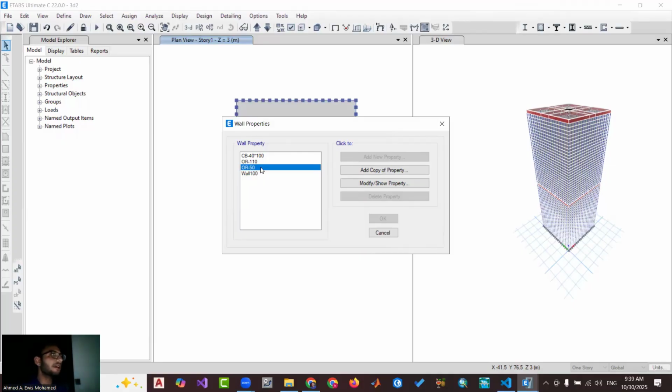Do you know the outrigger? Yeah. So the outrigger is the same as wall, but it's like a big wall that works as a column for this floor. We can put the outrigger at any floor, but with experience and trial and error, we can say the best place for outrigger is the top floor and the third top floors.